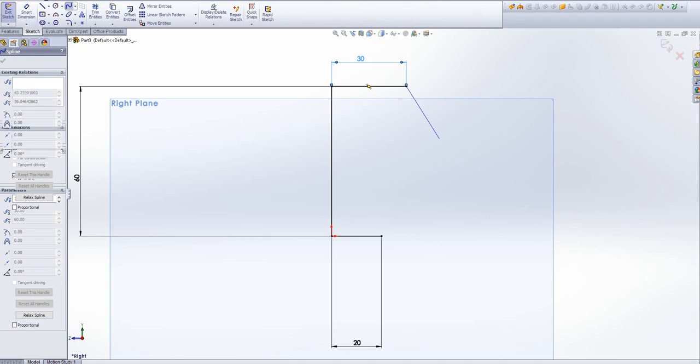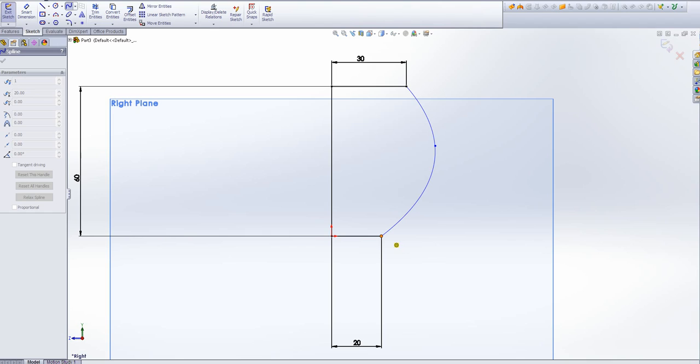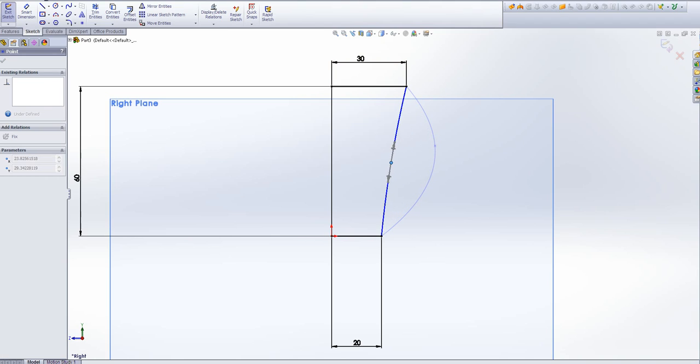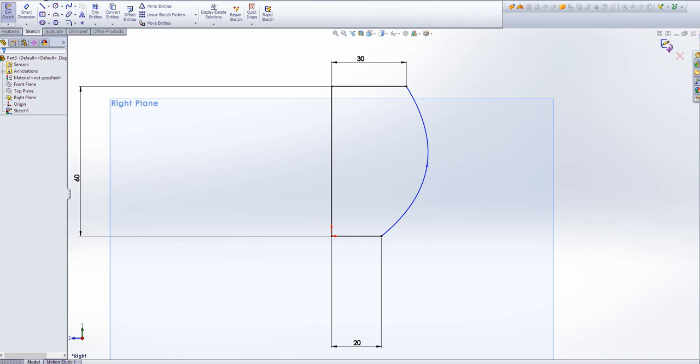Lastly, we're going to use a spline feature, and we're just going to come up and create a spline like this. You're going to connect obviously the top and the bottom, with this other point in between. You can change it to however you like. Maybe you want a bottom heavy coffee cup, or a more heart shape kind of thing. Whatever, I'll just go basic though, just a nice circular one. And once we're done, we're going to exit the sketch.